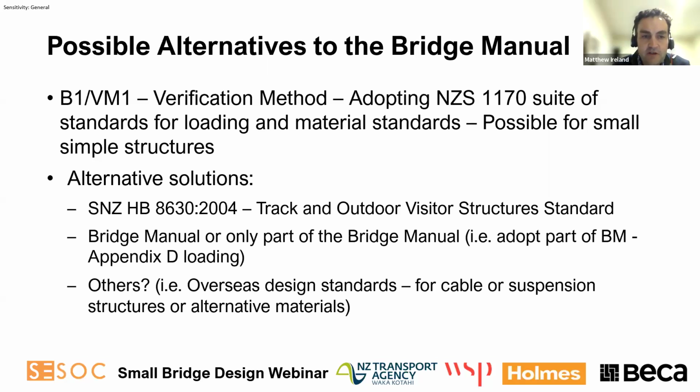Another option is to adopt part only of the bridge manual, and sometimes we might see this. Essentially using a verification method approach, but using the bridge manual for the design vehicle loading, say, such as the lightly trafficked rural bridge requirements of Appendix D, which Nigel was discussing just before.